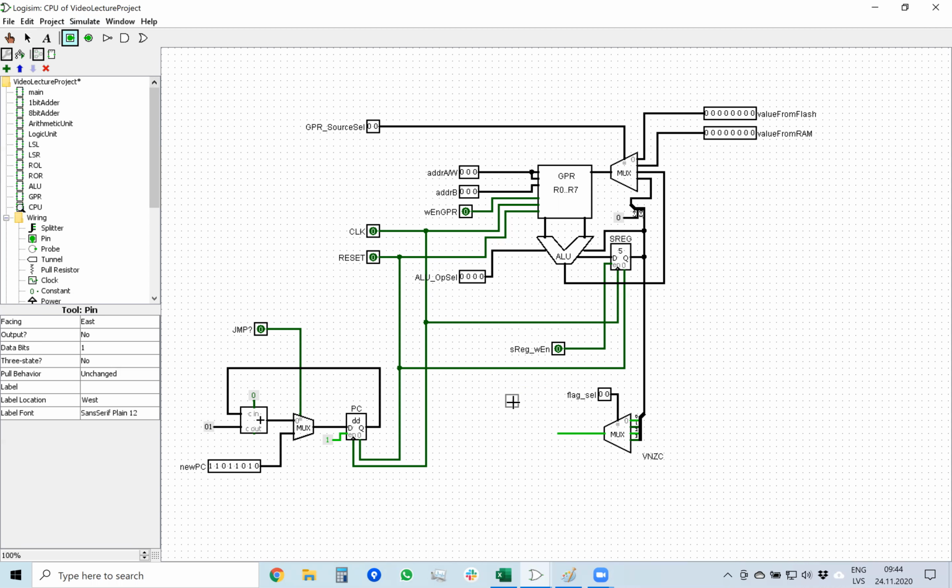So another control that we will have is flag compare value. So here I put an input, which is flag compare, the value of flag that we wish it had. And if flag value that we wish the flag had is the same as real value of flag, then we should get high value.